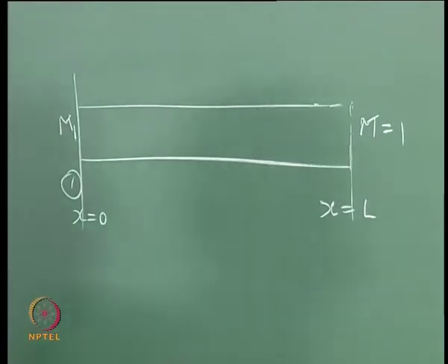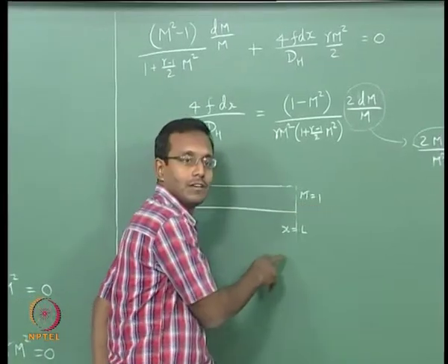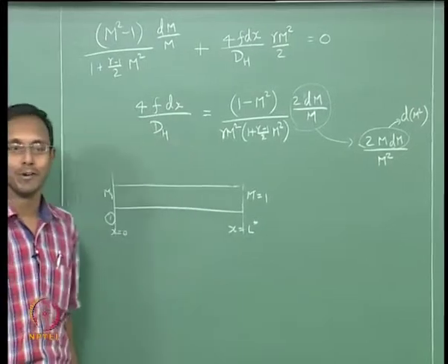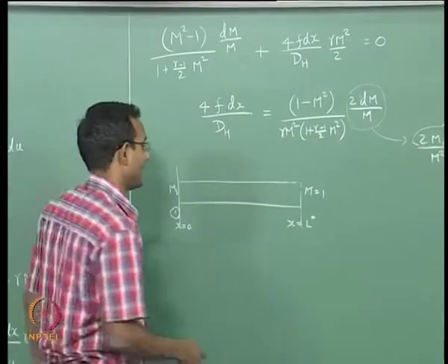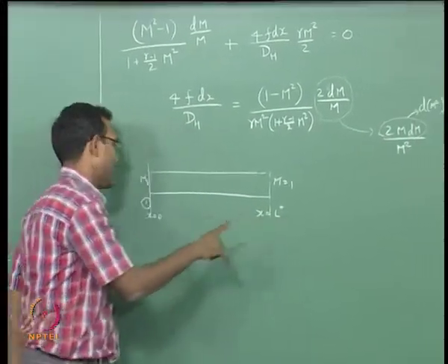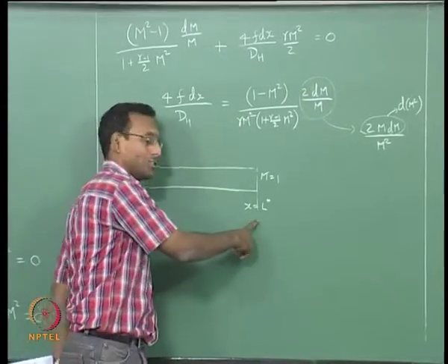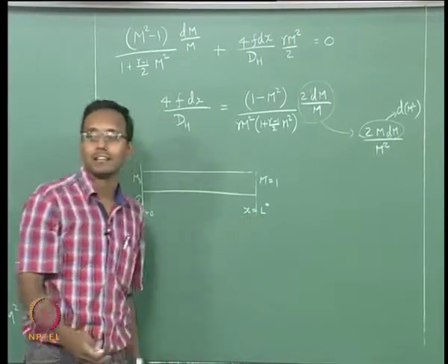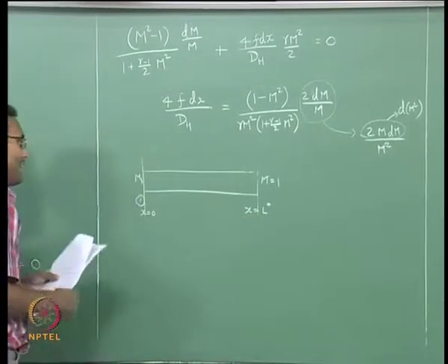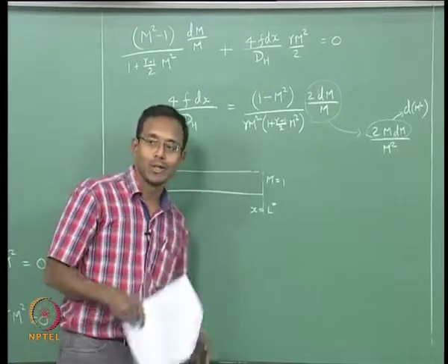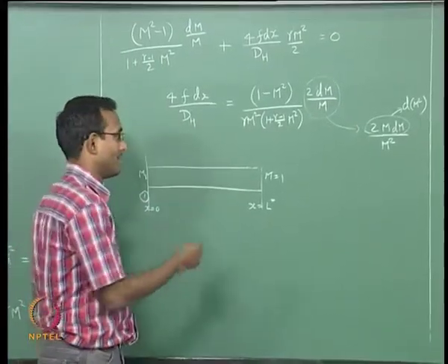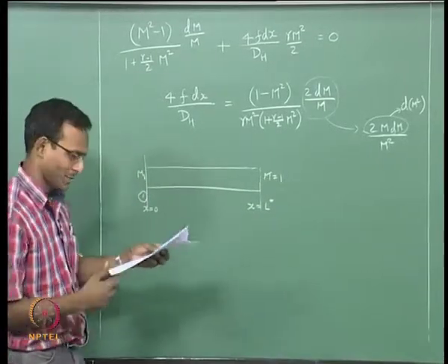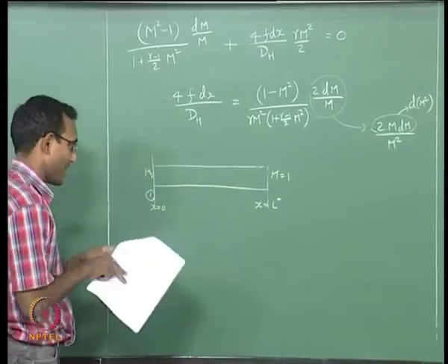And now, since it is m equal to 1, I will put a star on top of this L, as is customary. That says that it is the length that this flow needs to travel along this tube to become m equal to 1. This is a special length, it is not any length. We will later find that this is the maximum length that you can have. If you go beyond that, the flow will not be just doing the same thing, it will do something different. That I am supposed to discuss in today's class anyway. We will get back to that.